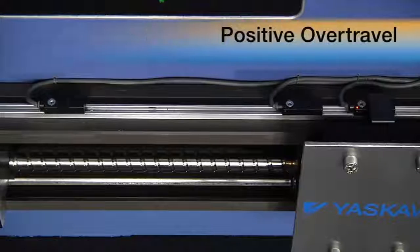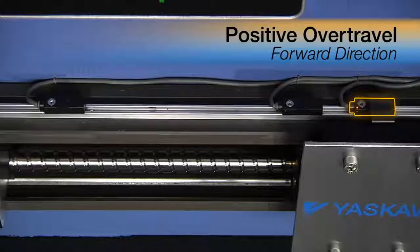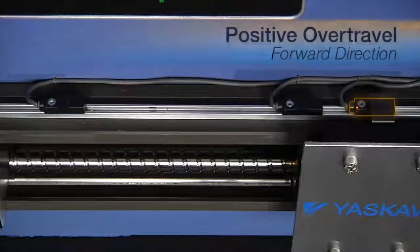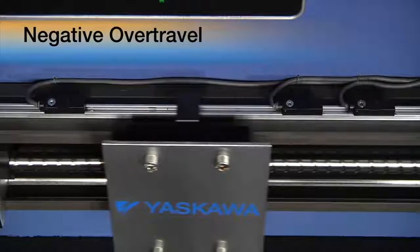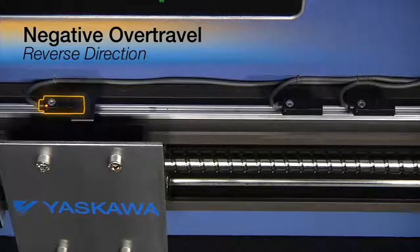Now, the positive overtravel sensor is connected to the amplifier input that stops motion in only the forward direction. The negative overtravel sensor is connected to the amplifier input that stops motion in only the reverse direction. So you can see that if these sensors get switched around, or if the direction of the servo doesn't match the direction of the machine, the motor might not stop at the overtravel sensor. Damage, or even injury might result.